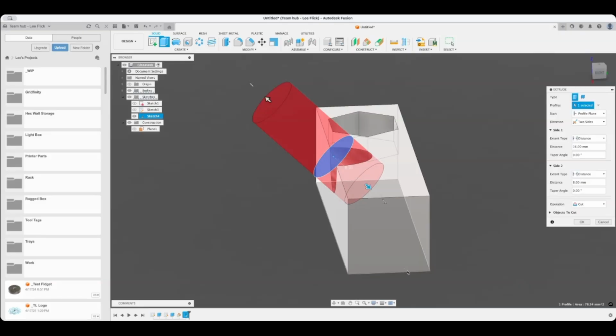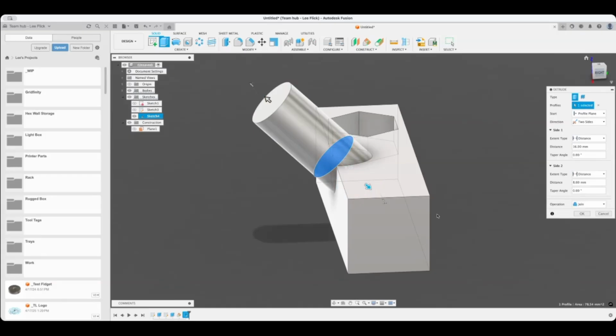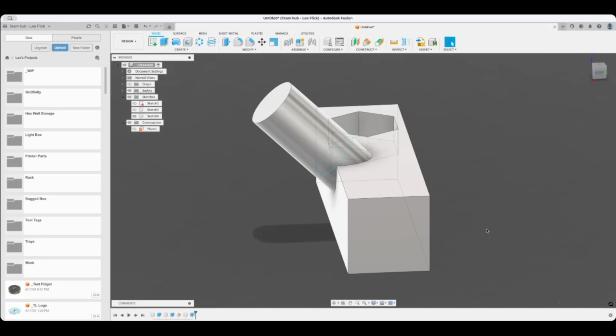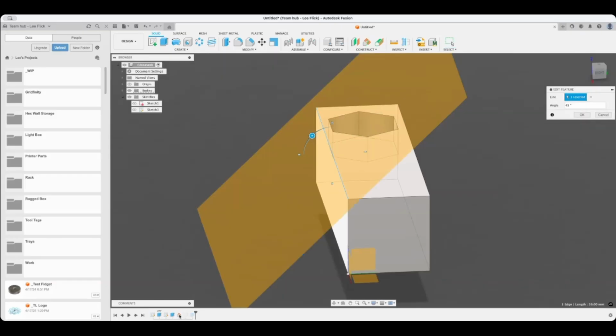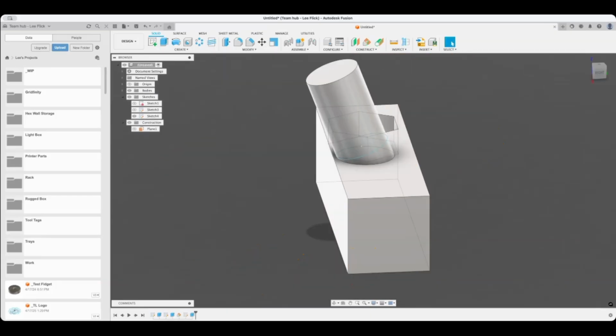We say to the cut command. So on that same box at the bottom, we change it to join. Got it. Okay. And then now click OK. We made an extrusion. Now here's what's cool. I did this. I go to fit it to something else. Oh no, the angle's wrong. I can go back to the plane command and change the angle to anything I want, and it'll move it to wherever I tell it to go.